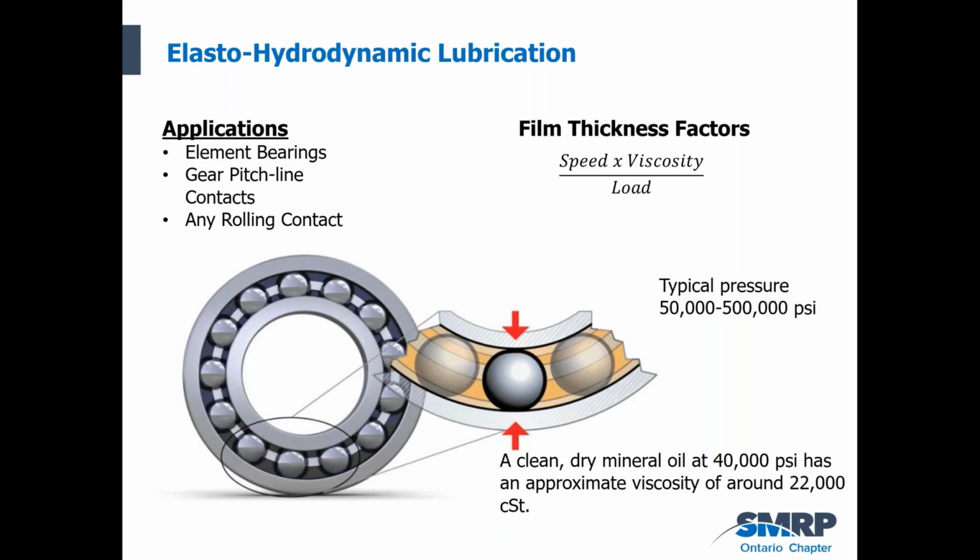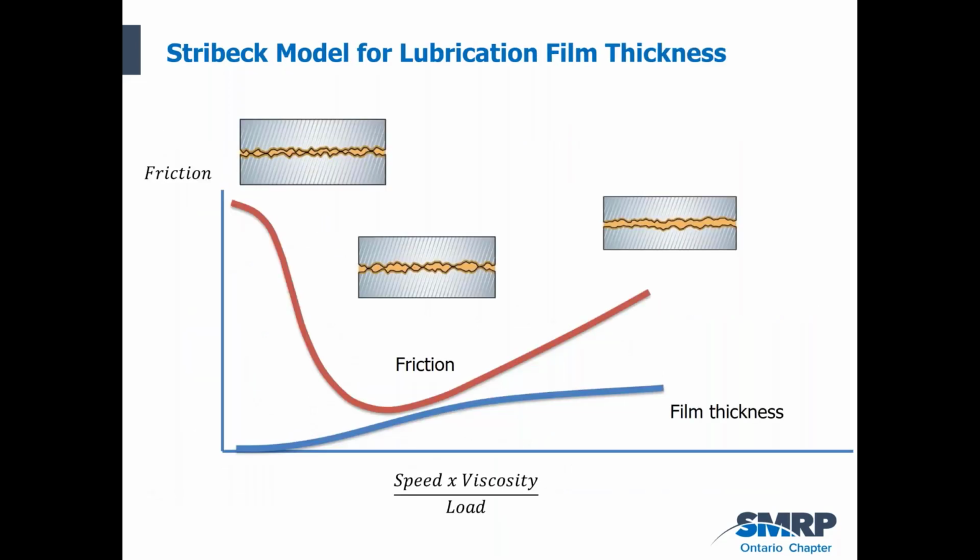The most fundamental property of getting good lubrication is to ensure that we have the correct viscosity for the applied load and speed. Those three factors, rotational speed, viscosity of the lubricant and operating temperature, and the applied load, go into helping us select the correct viscosity for the application. When we think about that, we can refer to a graphical representation of bearing lubrication that's referred to as the Stribeck Curve, named after the researcher that developed this theory.